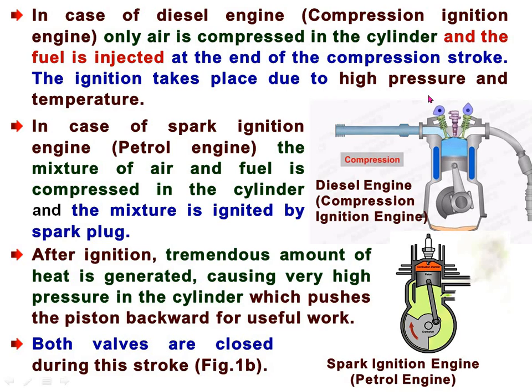At that time we are injecting the fuel with the injector in an atomized way, and that atomized injected fuel is ignited by the heat of compression. No need to have a spark plug for igniting the fuel in case of our 4-stroke diesel engine. But in case of a 2-stroke engine, the air fuel mixture is not so much compressed, so we need a spark plug to ignite the air fuel mixture.